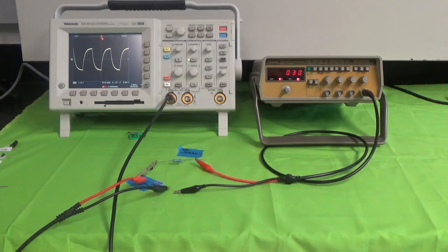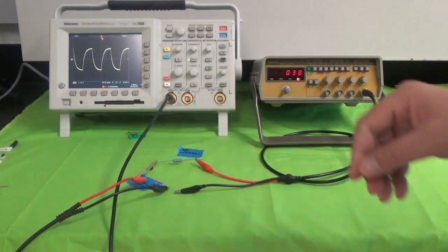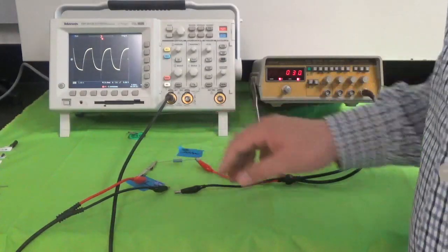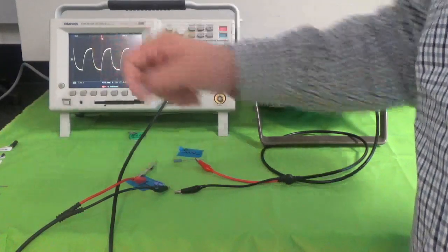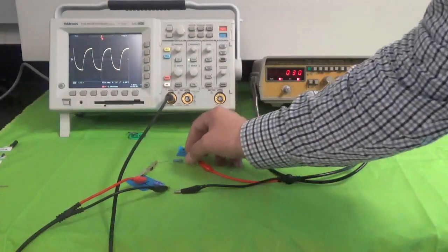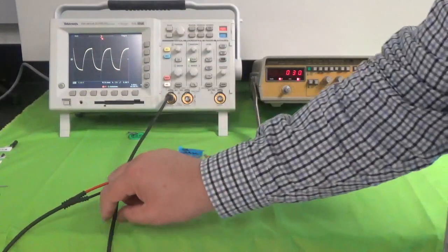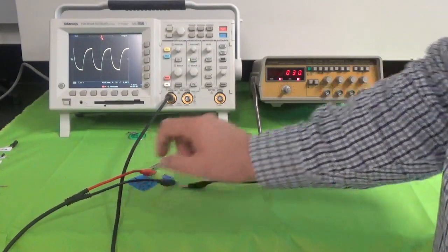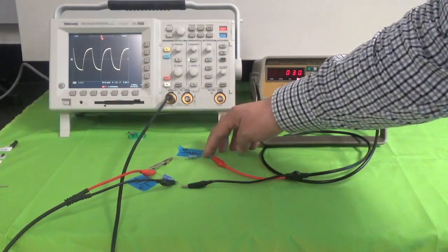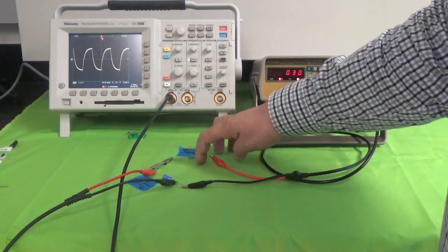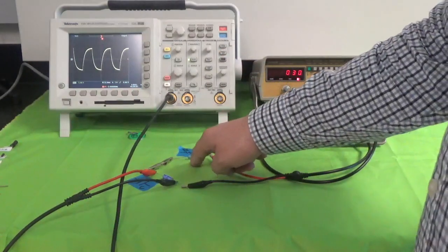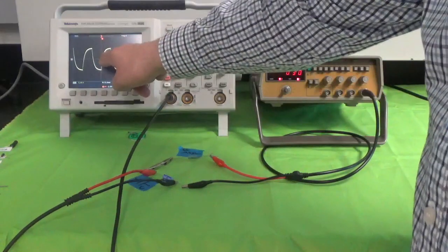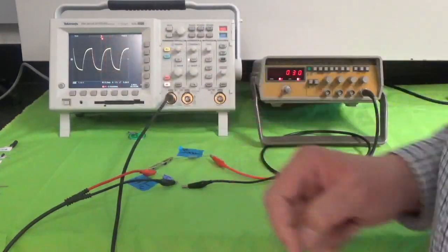and do this experiment. What we will do here is we will have the RC circuit, and we will try to figure out tau from here. The resistance that we have right here is 150 ohms. Okay, so let's go ahead now and read t half from the oscilloscope.